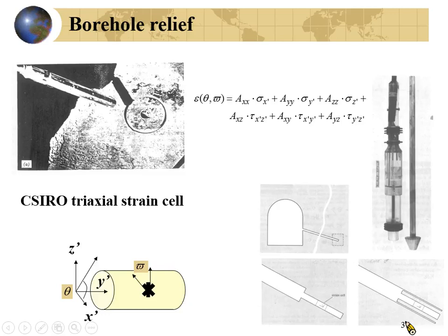So you can drill a borehole to a distance which is not influenced by the stress concentration. Then you will have your coordinate system, and you measure these 6 variables which are not influenced by the excavation of the tunnel. And you know the coordinate system which you want to obtain.